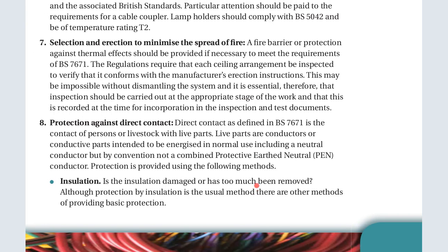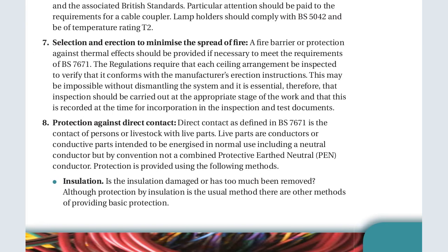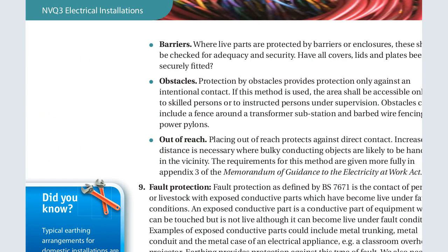Another one is protection against direct contact. That is, direct contact as identified by insulation damage, or where too much insulation has been removed. We have to check that.